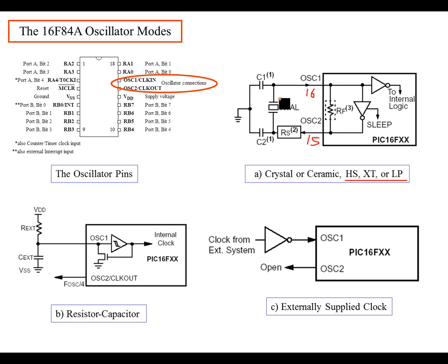Now, if you don't want to do that, crystals are sometimes a little bit expensive. Capacitors are fairly cheap, but you still have to have these 3 components on your board. If you want a cheaper option, something a little bit less stable as far as having a fixed frequency, this is a very stable fixed frequency. Not going to have to worry about this one, as long as you keep these wires short. Now, that is something to be considered.